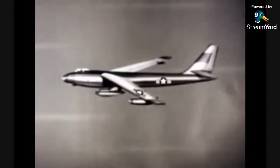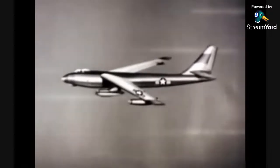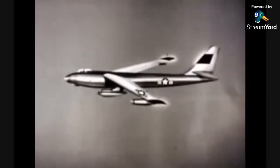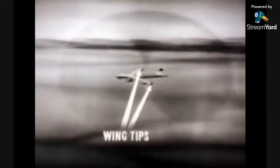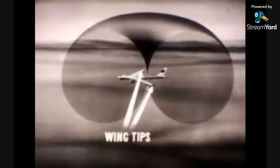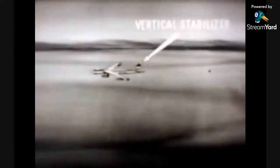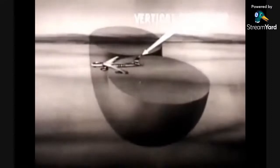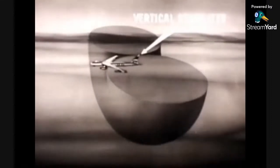As with other antennas, here too, drag is considerable, and on fast-flying jet aircraft, the antenna is recessed. Two of the possible locations are in the wingtips and in the vertical stabilizer. When it is recessed in the wingtips, a well-defined pattern is produced. When the same antenna is recessed in the stabilizer, it is usually in a vertical position. The resulting pattern is again well-defined, but is oriented differently.